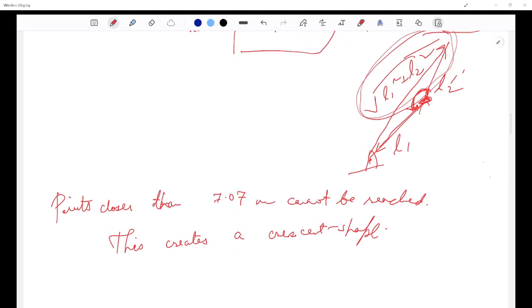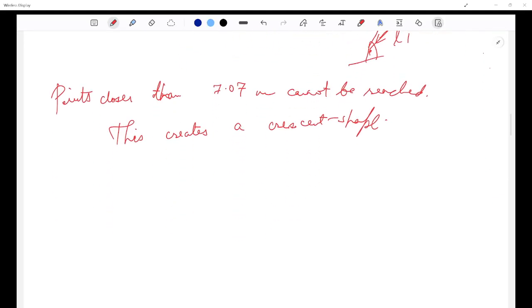Because theta 1 lies between minus pi by 2 and pi by 2, the arm sweeps from downward vertical through the positive x direction to upward vertical. This is what theta 1 takes care of. So this is exactly a 180-degree sweep centered about the x-axis.